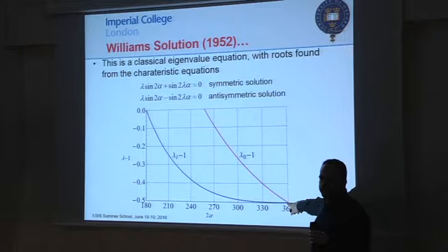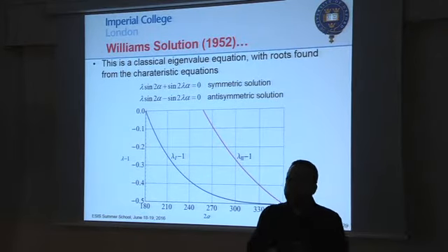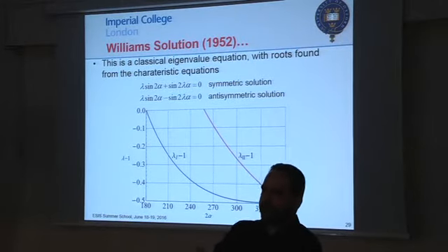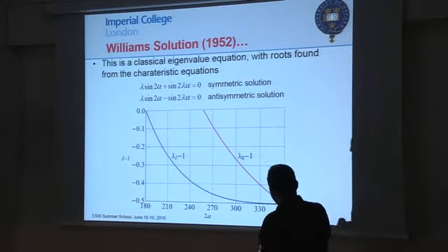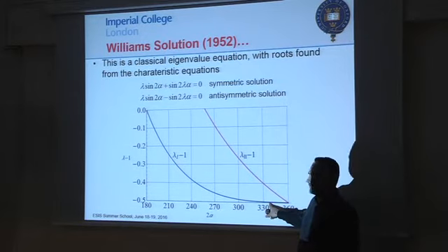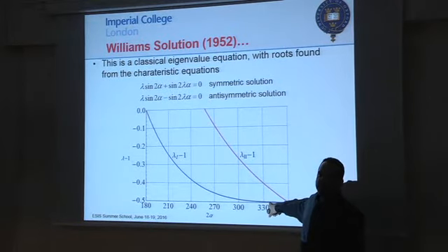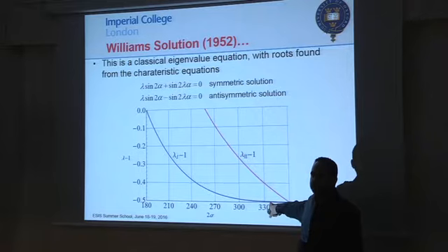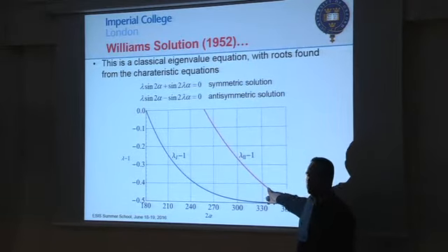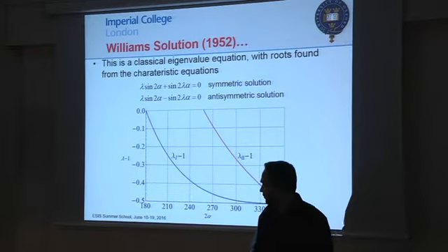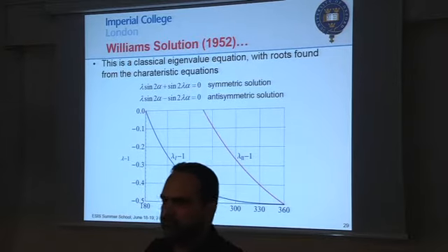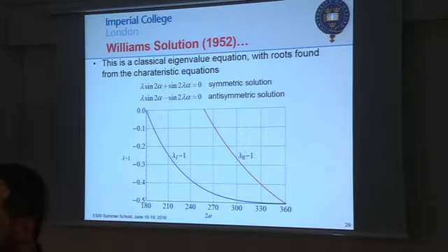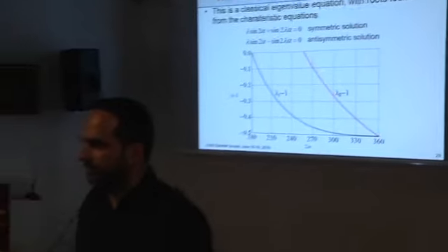Now, as soon as you start opening, the notch becomes 10 degrees wide, you are about at 340, you're here. The singularity in mode 1 is almost still 1 over square root of r. Now, in mode 2, it's not. In mode 2 it's not 1 over square root of r, it's 1 over r to the power of 1.41. But let us assume that the sharp notch is working under mode 2.